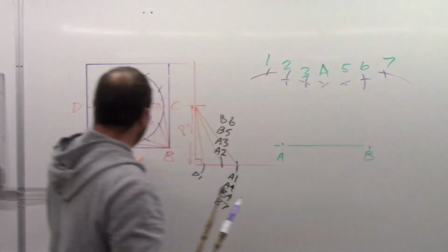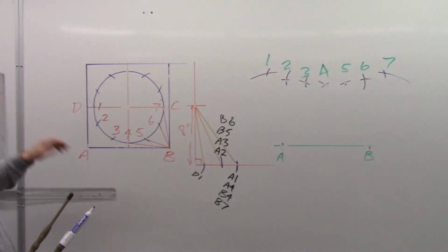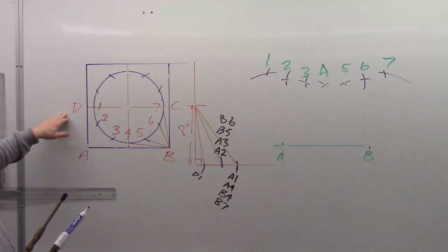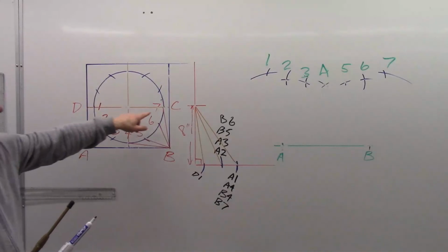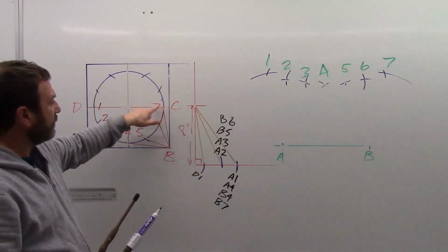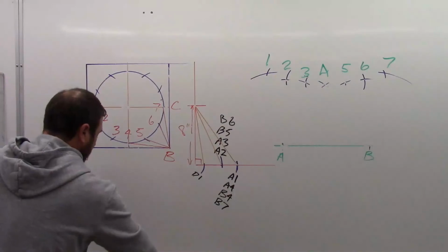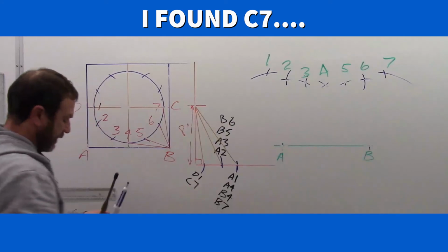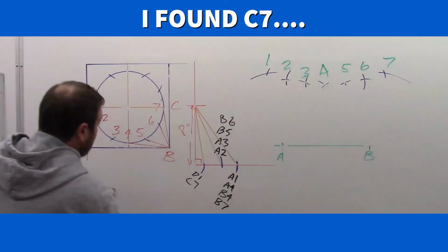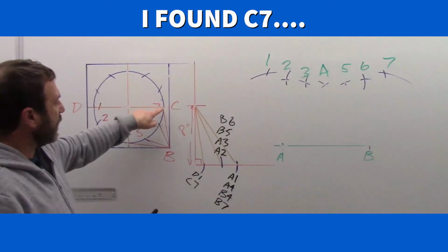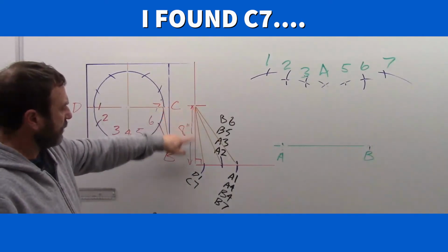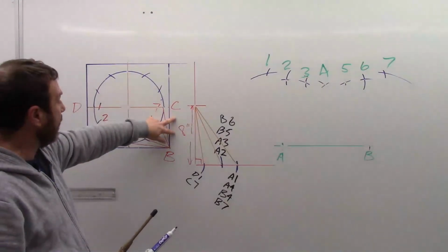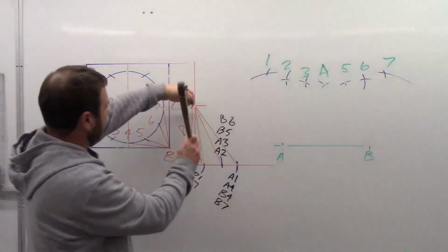Okay, but we're not complete at the bottom yet. We need to still create C and D. Let's keep on this side. C7 we put into here. That one was with D1 because it's our line of symmetry. So we need to triangulate point C7 from our true length diagram, and then BC, which is a true length here. So I'm going to pick up C7 first.